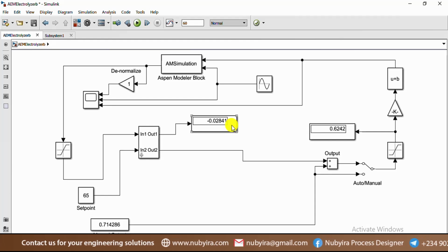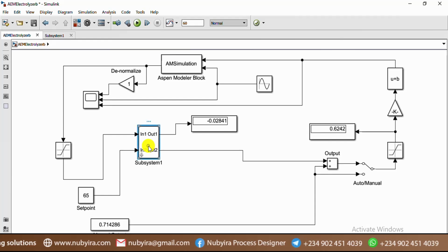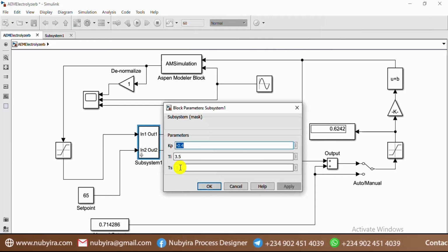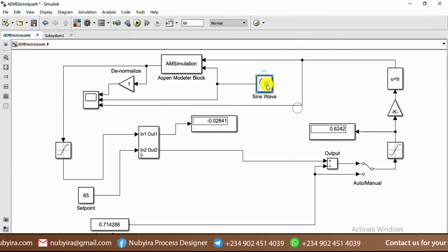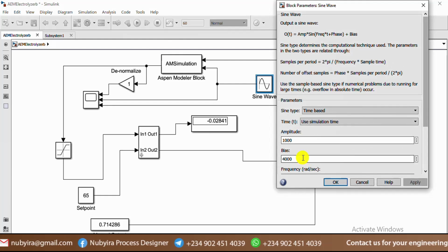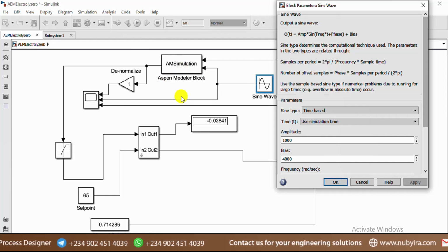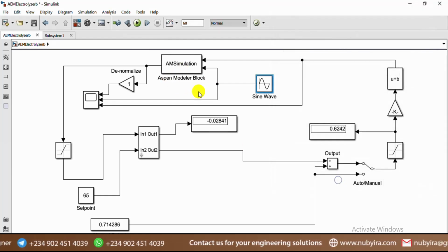So I think in order to make the model work accurately and efficiently, the sampling time can be adjusted, and the sine wave too can be modified. It might be some kind of bug in the solver, the integrator of the Simulink, and the step size that is chosen, as you can see in the Simulink model.